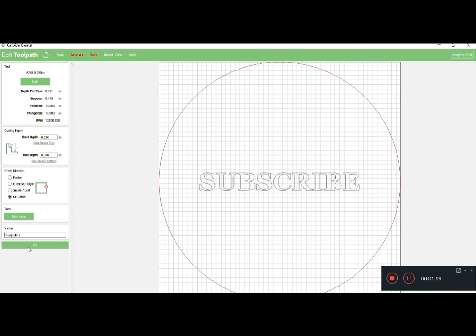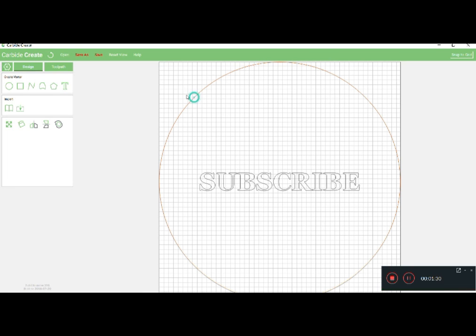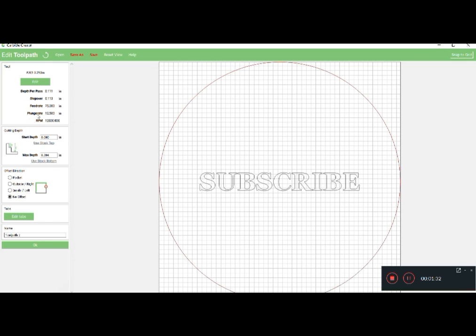Now, if you remember, we went back to our stock thickness right here, and you can see it's 3/4 inch. So I want to cut this out completely. Because we already had that set up, I am going to go to my toolpath and set max depth 3/4 inch. But here's the thing, we have a spoil board down on our machine, and sometimes it might not go all the way through, so we're going to make it a little bit deeper. Because we have a spoil board, it's not that big of a deal. So we're going to go .76, okay, and we're going to hit OK.